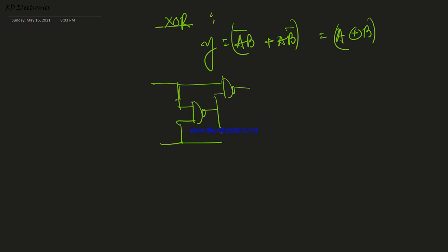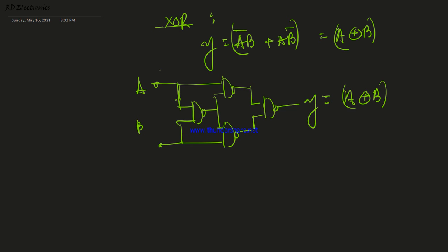This is the configuration of logic blocks. We can also design using FPGA. In my FPGA course lecture videos, please follow the XOR gate operation or NAND gate operation in VHDL language. But in this lecture we only talk about the internal technology using diode transistor logic.